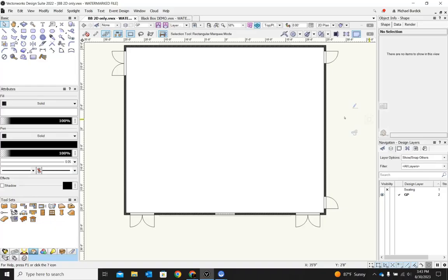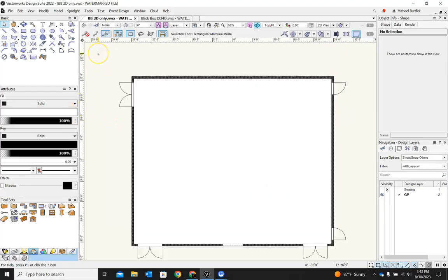So we have already built everything in a two-dimensional space. That's what we're looking at now, our two-dimensional ground plan view of the black box space. I think we'll start with that space because the process is going to be a little simpler. And I'd like to actually show you 2 different ways of making walls and bringing things into 3 dimensions today. You've already gone through the tutorial with some basic 3-dimensional tools, and we're going to use a lot of those when we get into the proscenium.